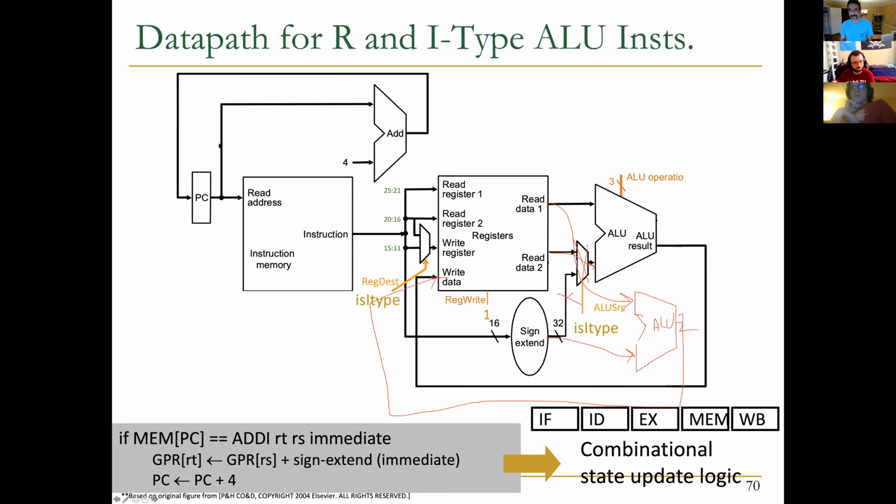In single cycle, you have one cycle, you do not have this flexibility. But in general, yes, if you had a more flexible design, you could gain some time efficiency if you add two ALUs, right? Because you have two resources now to do some calculation for you. Okay, that you can figure it out to increase the parallelism level and increase the time efficiency. Is there anything else that might influence and you would prefer one over another?